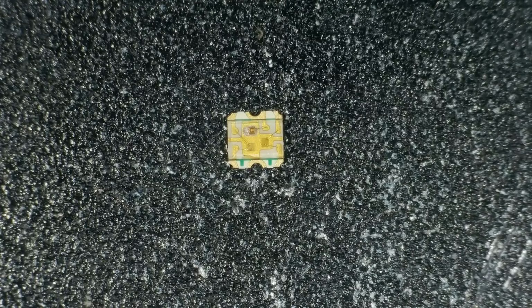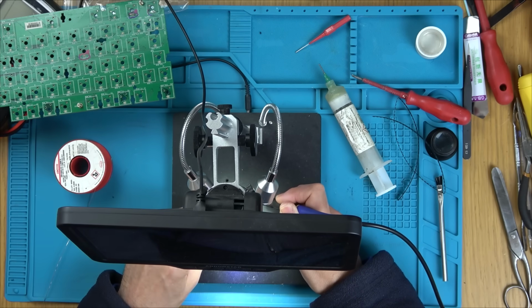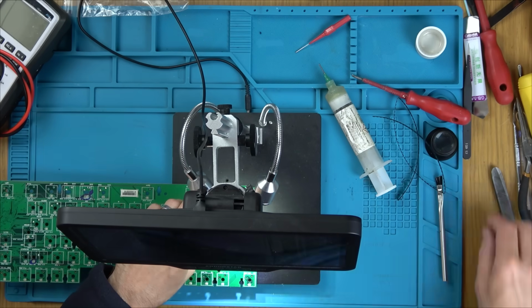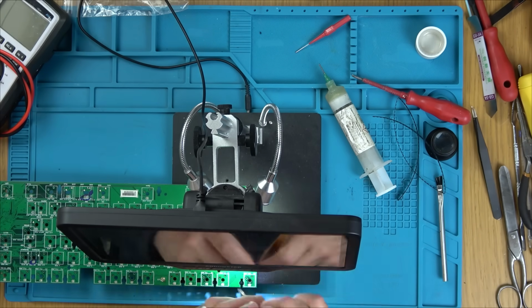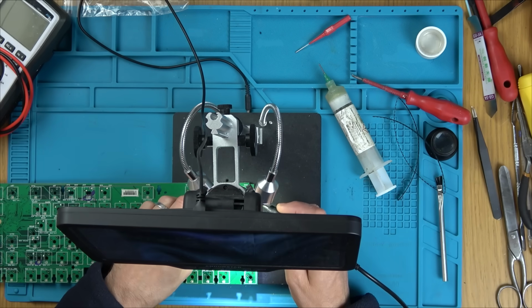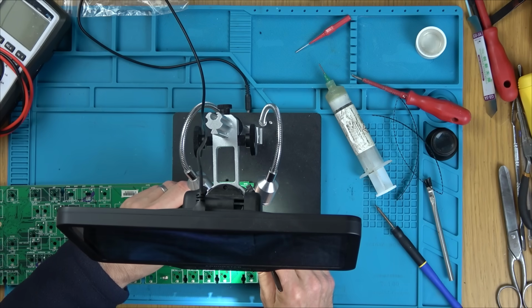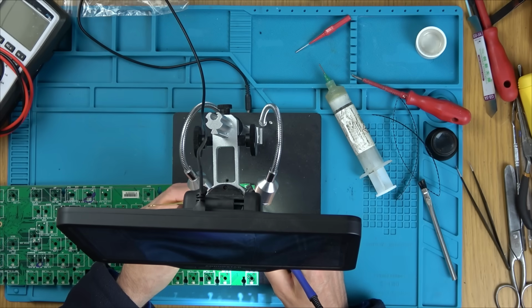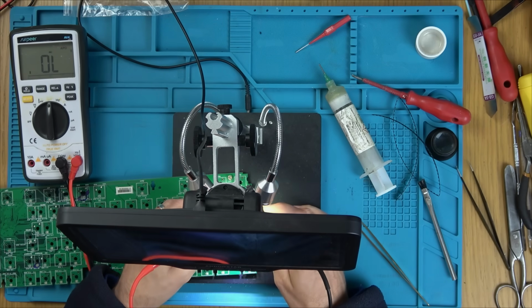But anyway, I did solder them in. I soldered in, I think, 9 of them, and I only wasted a couple of them, and I think there was another 2 that looked like they'd been cut incorrectly. So not bad, because I got 100 of these for next to no money at all. So yeah, if you've got time on your side, you can repair these keyboards without too much expense, which is good. Anyway, I've replaced the ones that I know are not lighting up properly, and now the next bit of footage you're going to see is when I'm plugging it in to see if it's made any difference.